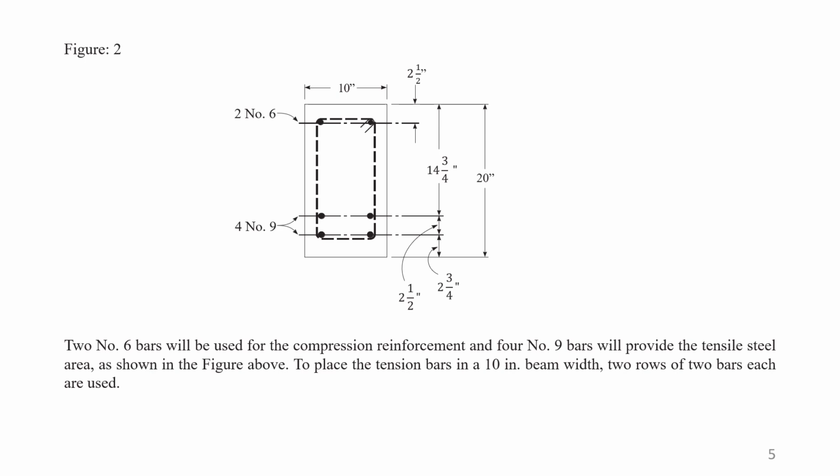There must be a clear cover. Here the requirement is 2.5 inches, but for calculating and making round figures, we have used 2 3/4 inches.